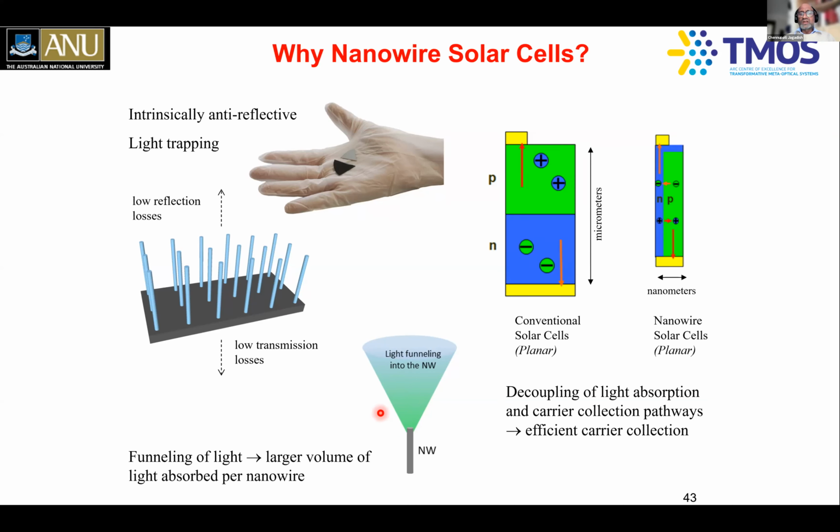And again, we looked at this nanowire diameter and then the diameter to pitch ratio. We can see that about 150, 160 nanometer diameter is very good from the point of view of creating the maximum amount of current. And then also the diameter to pitch ratio should be somewhere around 0.5 or 0.6 or so. You can see the individual plots, which I'm showing you here.